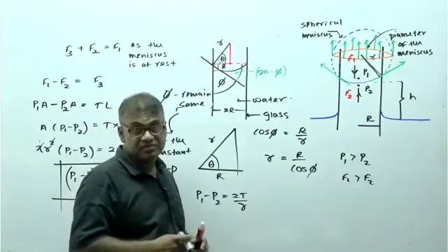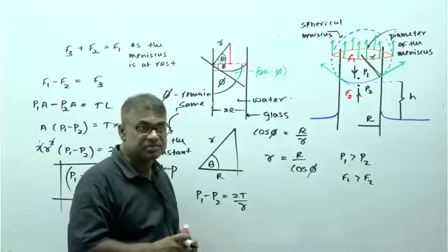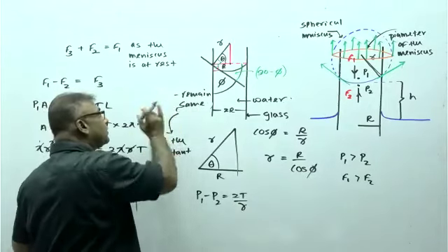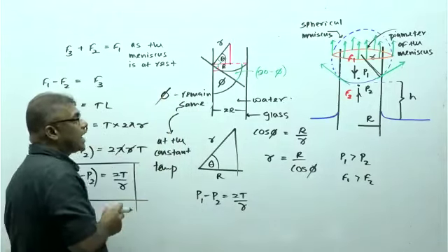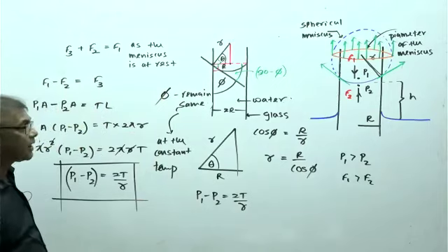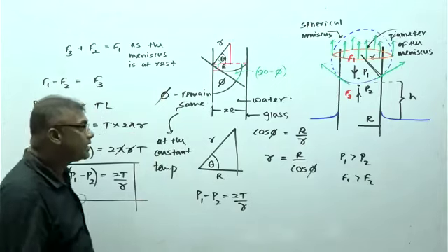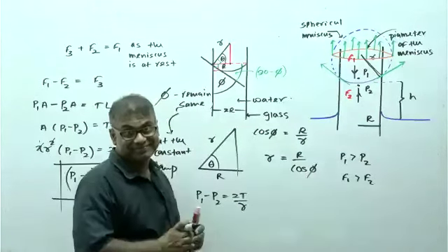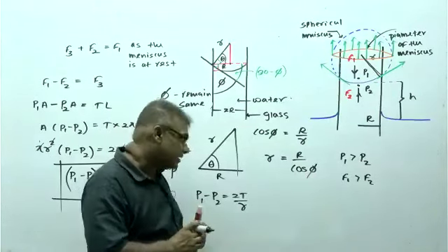When the temperature is changed, the molecular configuration and energy change, so the angle of contact will definitely have different values. The angle of contact is a constant for a given liquid and material, even though the radius of the tube is changed.